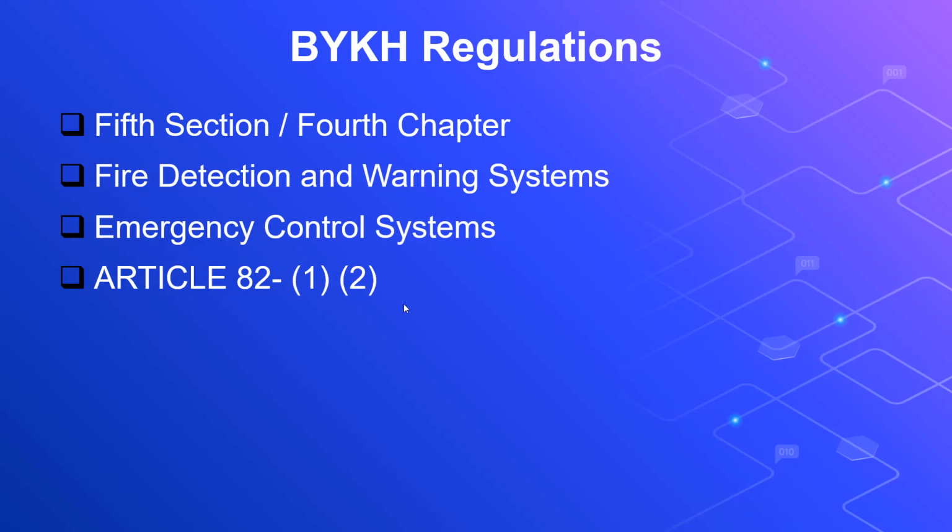Emergency control operations are carried out with the control units that are within the hardware and software integrity of the fire alarm systems. Systems and devices related to control systems that could be subject to the control and command operations by other systems such as building automation systems must not in any way hinder emergency control operations from the fire control panel in the event of fire or similar emergencies.